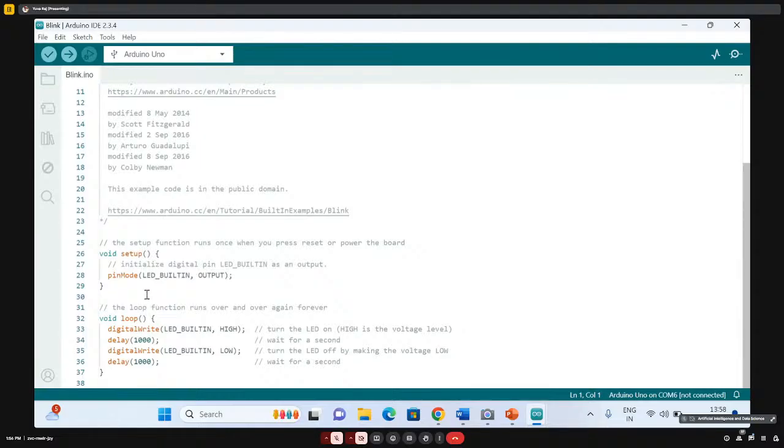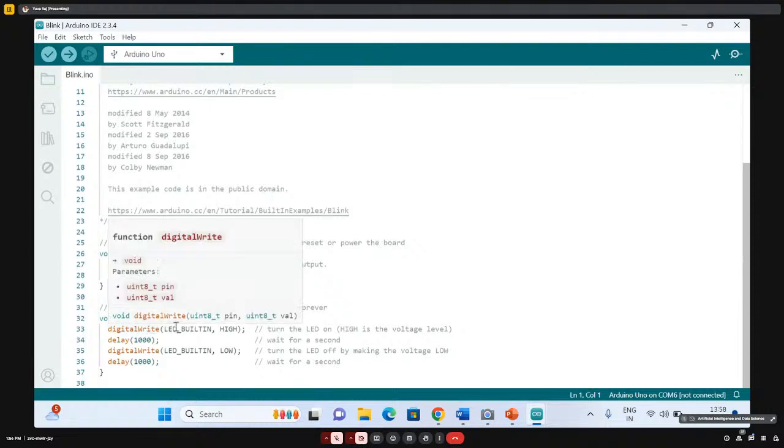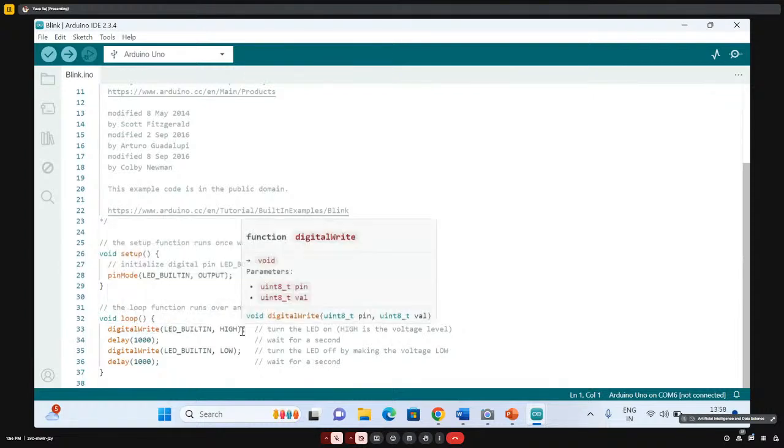And then the next one is void loop. You give the pin number, and the LED will go on and off. First the LED will be on, that is the HIGH mention, with a delay time of 1000. Then you choose LED low, with a delay time also of 1000. Okay, let's see. I will show hands-on how to make the connection on the breadboard.